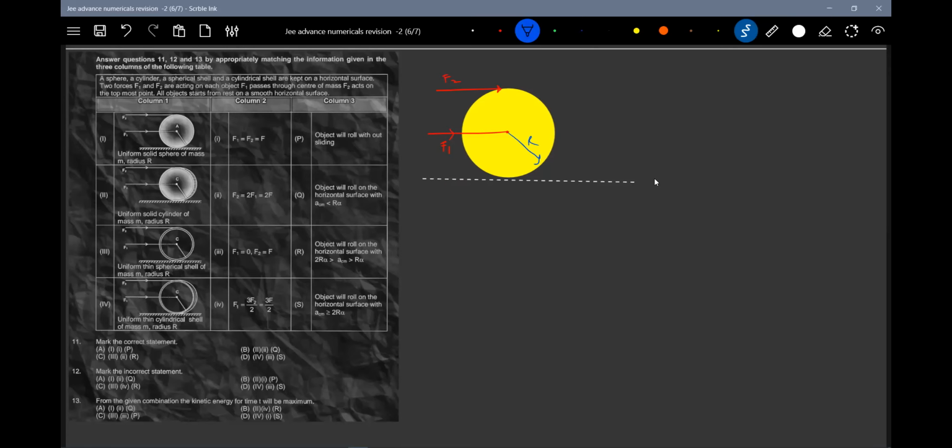Rigid body, moment of inertia about A we will consider like this. If you apply force at the highest point, this F2 I can bring it here also. If you're getting confused, assume that only force F1 is acting, friction will act backward. Then if you apply force here, the friction will be forward. So I'll take a risk of assuming the direction of friction backward.